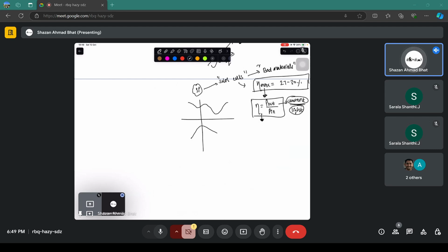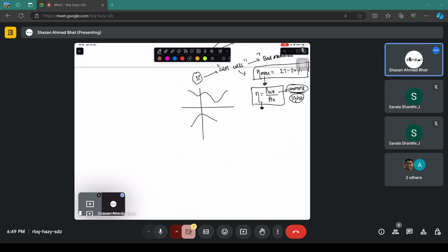The reason is because it's an indirect bandgap semiconductor. Because the electron has to go from this region to this region. Maybe it can go up to a certain mid gap region, or where there is some defective state, then other processes have to happen, which are the phonons. They can bring this electron to this particular state, and you have an electron hole pair generated.